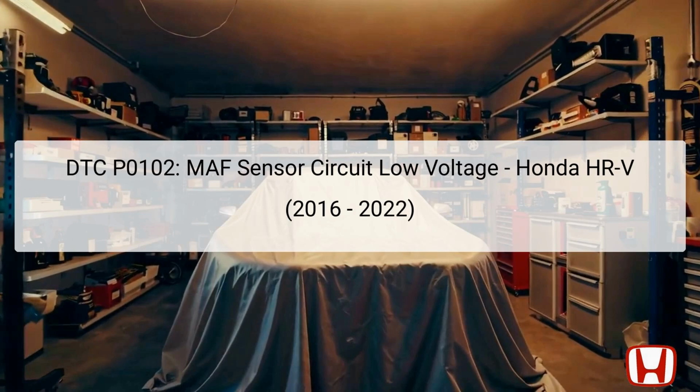The DTC P0102 indicates a low voltage condition detected in the mass airflow (MAF) sensor circuit. This sensor plays a vital role in measuring the amount of air entering the engine, which directly influences the air-fuel mixture essential for optimal combustion. A low voltage reading usually suggests an issue with the sensor itself or the wiring leading to it. Often, this could result from wiring defects or even a faulty sensor.